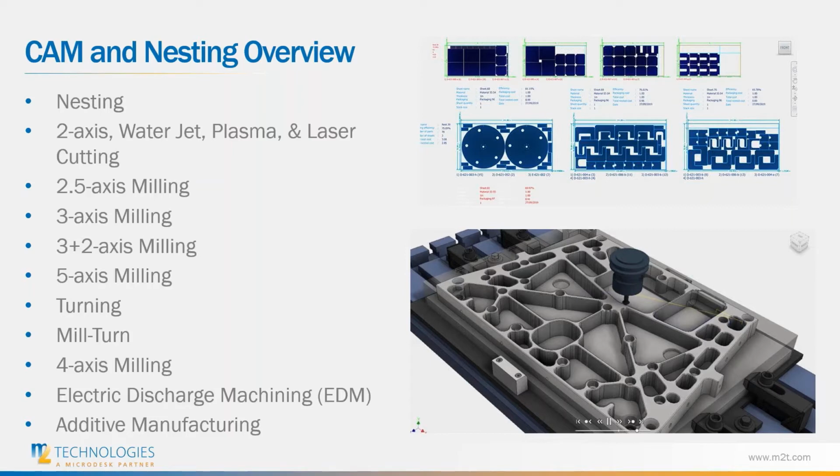From mill turning, the next step up is the 4-axis milling, which has the turning operations as well as the mill turn rotating cutting tool. But within 4-axis milling, the cutting tool has more capabilities similar to 3-axis milling, using indexing along that 4th axis with the lathe.